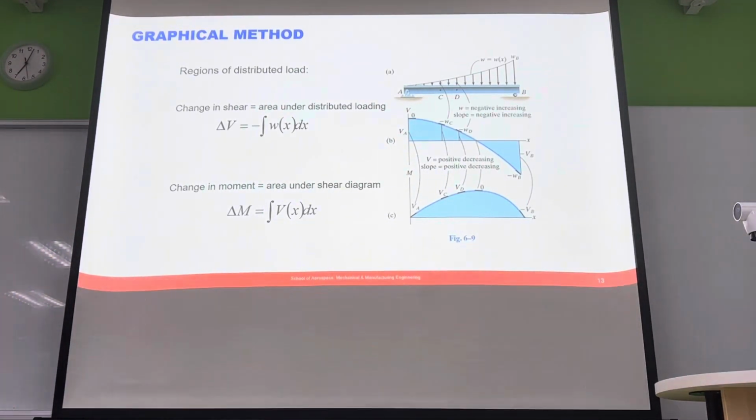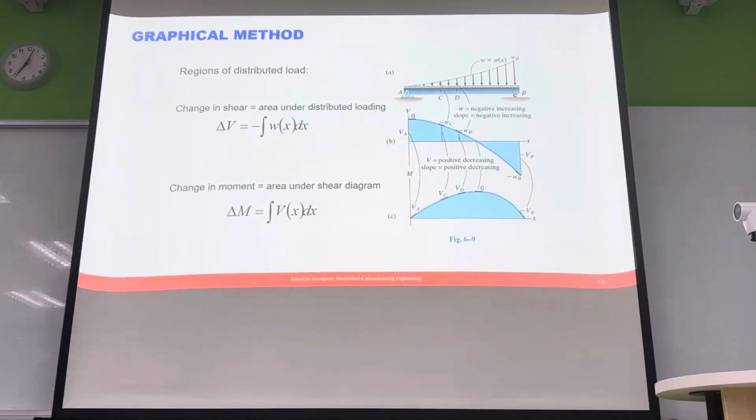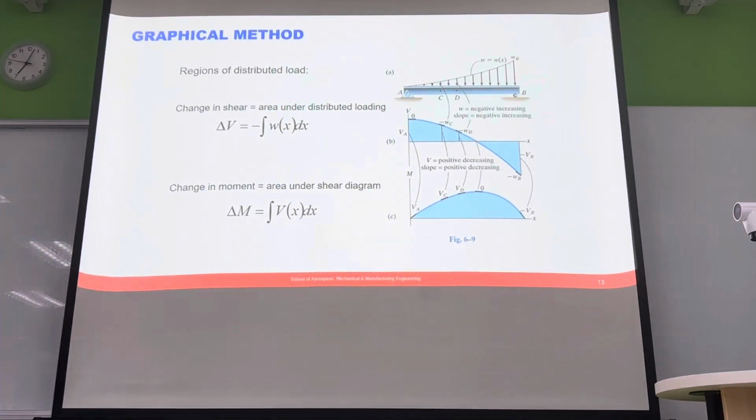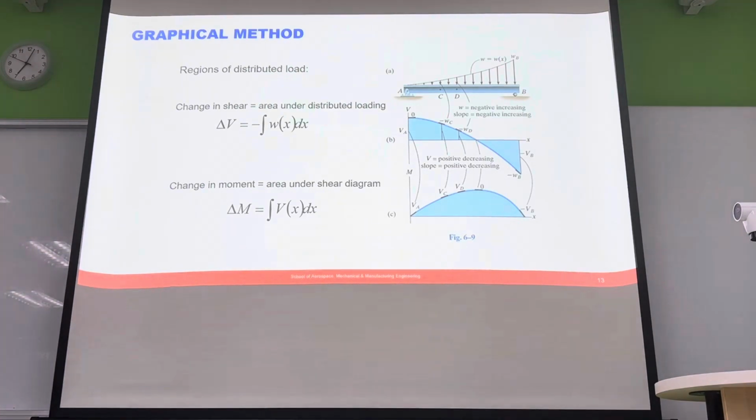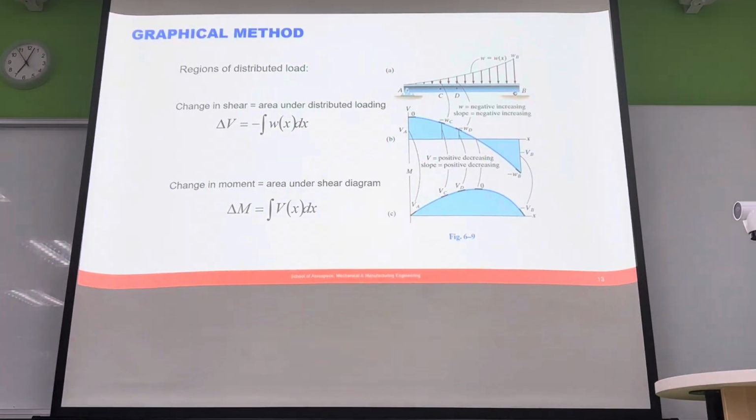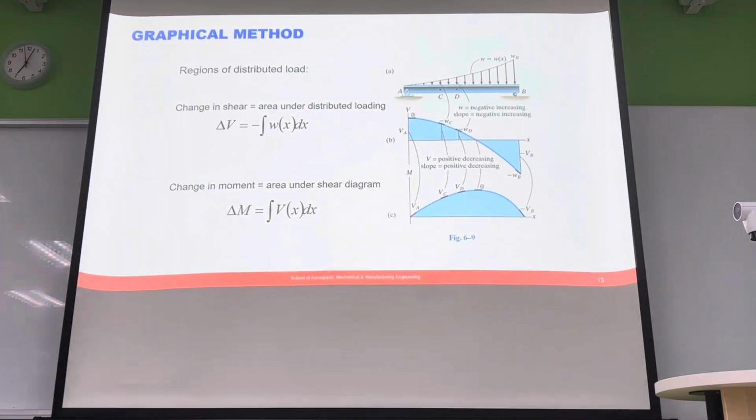And then obviously here, because we have negative values, we have negative slopes, negative gradients. Which becomes very, very useful. And also bear in mind that you can do a similar relationship between bending moment and shear force as you do between shear force and external distributed loads. Bearing in mind that there's a negative sign here, which we'll get into in a second.